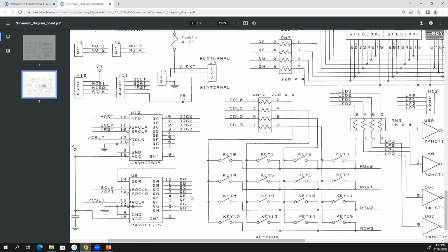In order to connect them together, I have to connect this one to this one, okay? By doing that, you connect the last flip-flop with the first flip-flop here. So every chip is going to be 8. Once I make the connection this way, these 2 chips are going to be like 1 chip with 16 flip-flops. You got what I'm saying?